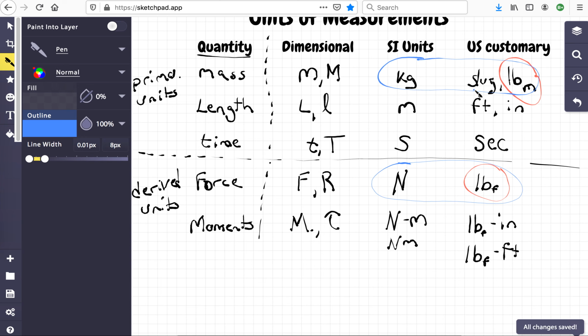Normally a slug's not in this course, but that slug you might hit in thermo and others. But they do get confused often. Please don't confuse them. By now you should understand the differences. I've seen over and over again when it's asking for a force, students want to give me the units in kilograms, which is a quantity of mass, not a force, and it is completely incorrect if you do that. So please don't make that mistake.